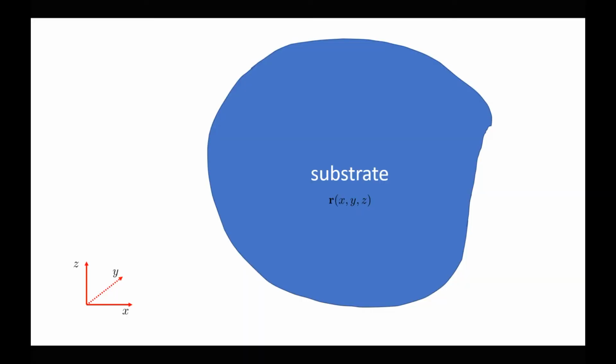We start with the geometry of the problem. Given a substrate, the surface can be expressed in normal Cartesian coordinates x, y, and z. However, for curved surfaces, this gets very complicated. Thus, we use a curvilinear coordinate system. This involves examining the lines of principal curvature and parameterizing these using the variables s1 and s2. This lends itself naturally to the problem, as the principal directions we have chosen are the directions where the curvature of the surface takes its maximum and minimum values, and these are always orthogonal to each other. In this way, we can now write any part of a substrate surface as a function r of s1 and s2. Finally, we choose our last coordinate so that it is perpendicular to s1 and s2.